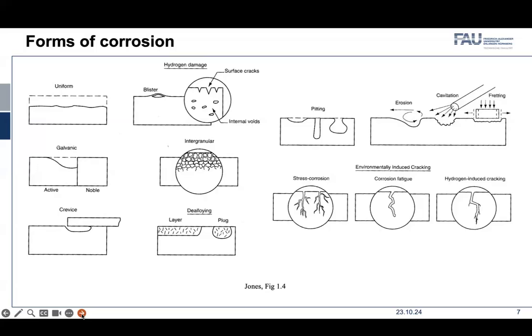Around the carbide there is not enough chromium to form the passive film, because in stainless steel it is the chromium alloying that makes stainless steels actually stainless. People usually say you need 12% chromium to form a passive film. Pure iron, under normal conditions, is not really passive. Maybe in sulfate containing environments iron is also passive, but in real environments, iron tends to corrode. So you add more chromium to the material. If you have at least 12% chromium, then you are able to form this very thin, nanometer thick oxide scale or film that protects the material.